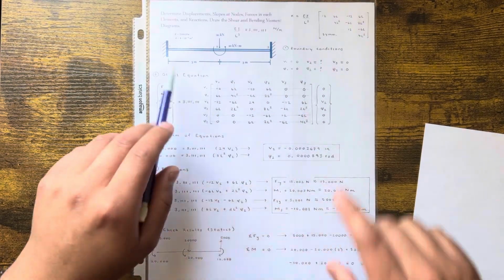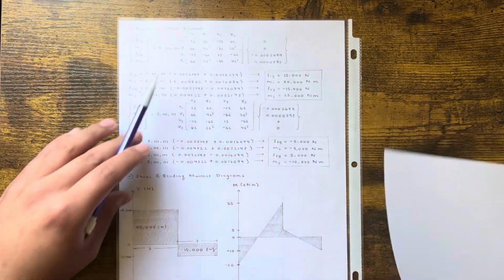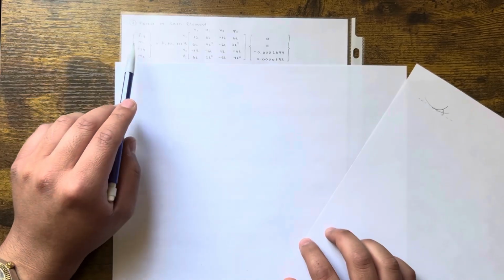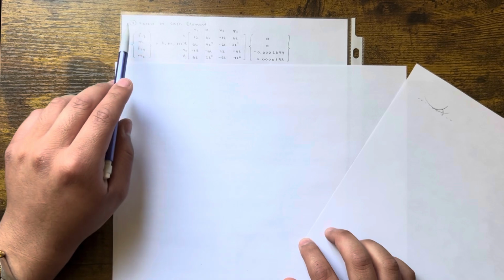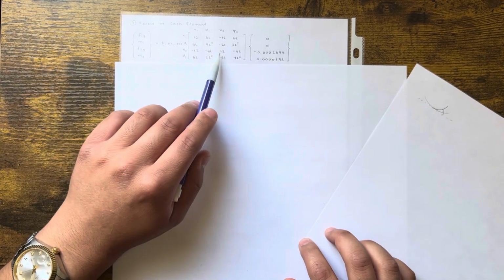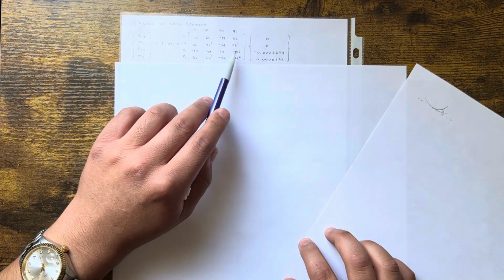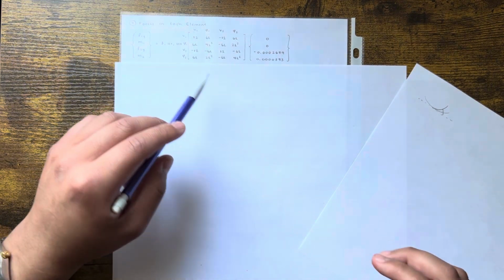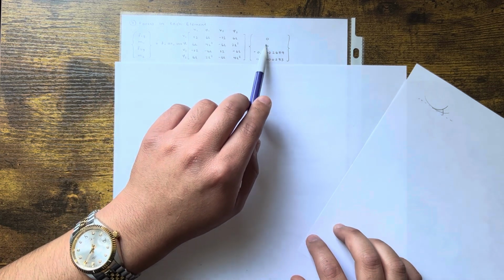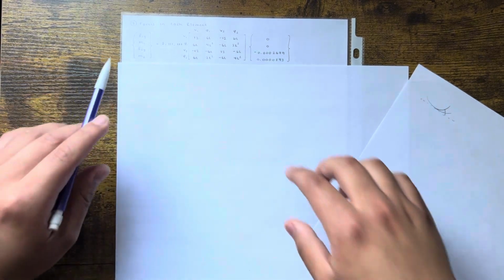And then you're going to use, so in this case, we're going to do element 1. It goes from nodes 1 to 2. So let's go ahead and do that here before I show you the answers, right? F1y, M1, F2y, M2. That's element number 1. It goes between nodes 1 and 2. It's equal to the stiffness. Look, 12, 4L squared, negative 6L, negative 6L. I didn't use 24, 0, 0, 8L squared. Okay? So once you got this stiffness matrix, you know V1, Phi1, you know V2, Phi2, right? We calculated those on the previous page, so just plug them in and do the same thing.